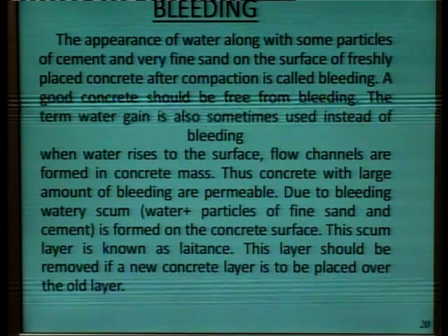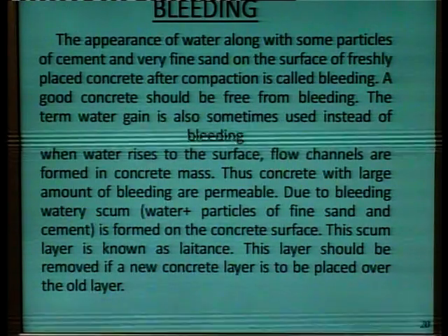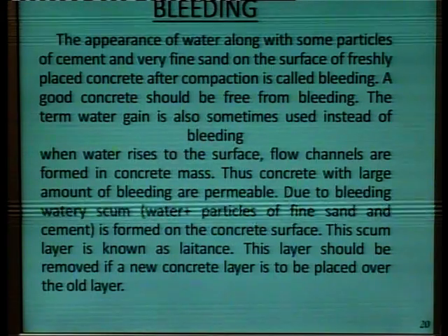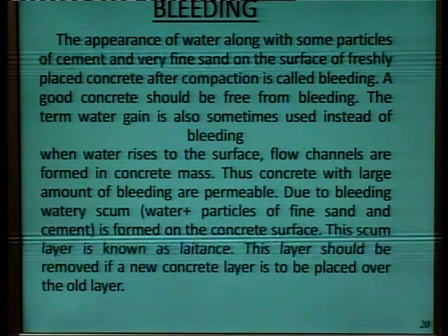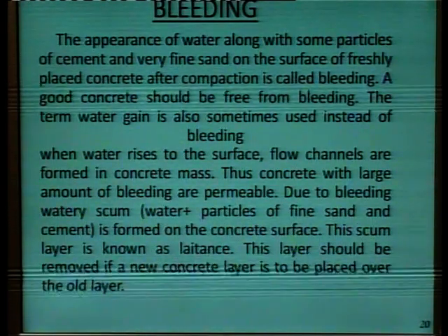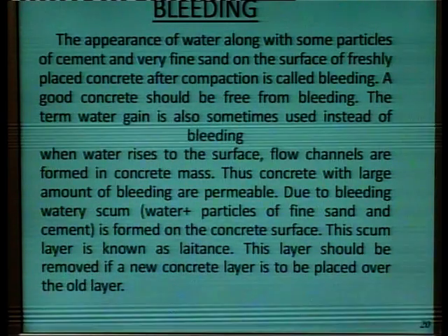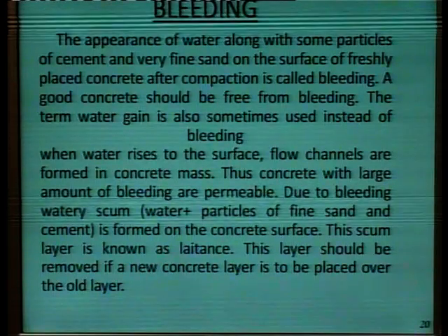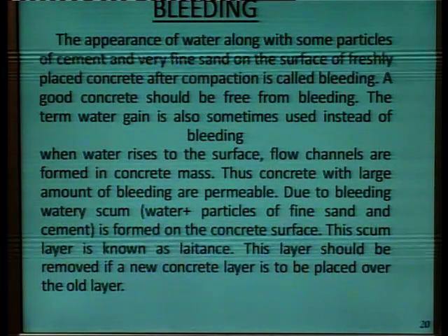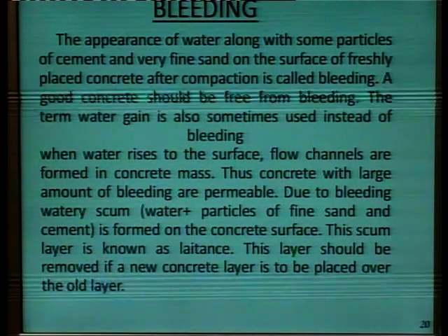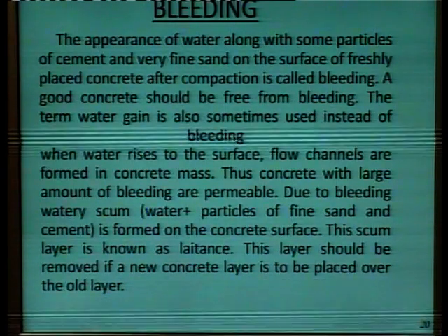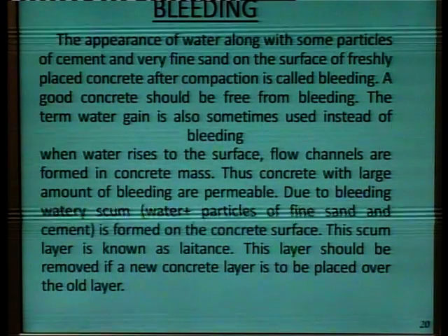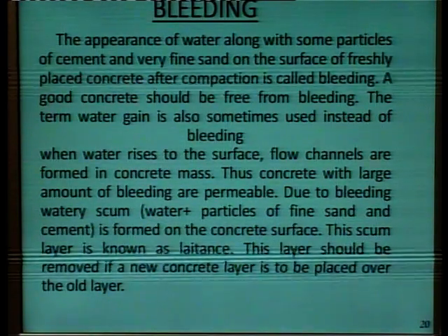This scum layer is known as laitance. This layer should be removed if a new concrete layer is to be placed over the old layer.